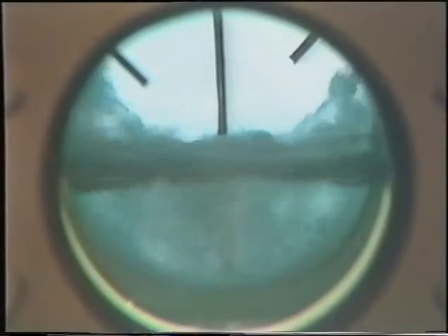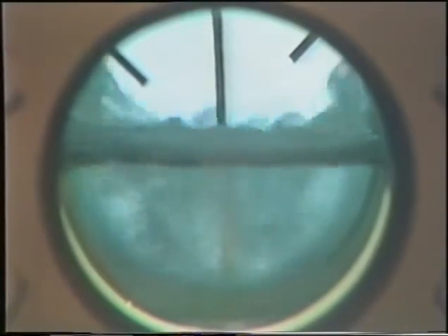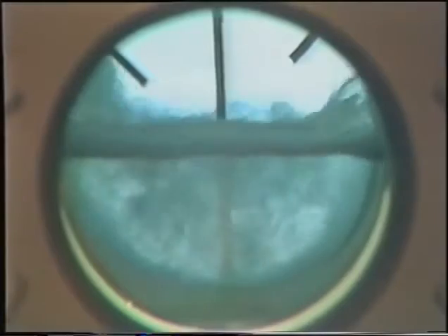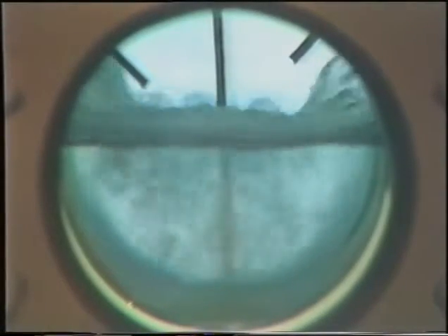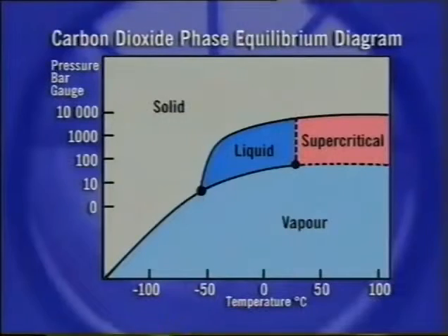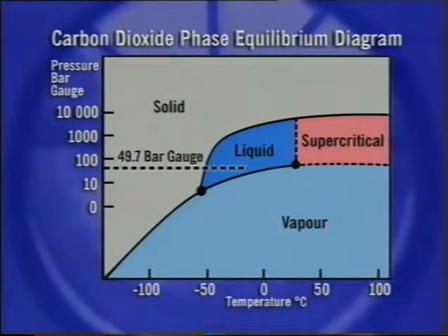Venting CO2 from the vapor phase above the liquid allows more liquid CO2 to decant from the supply cylinder into the cell, raising the liquid level. When the cell is sufficiently full, both valves are closed. When the cell contents have settled, the liquid and vapor are in equilibrium. This is represented by the cross on the liquid-vapor equilibrium line.